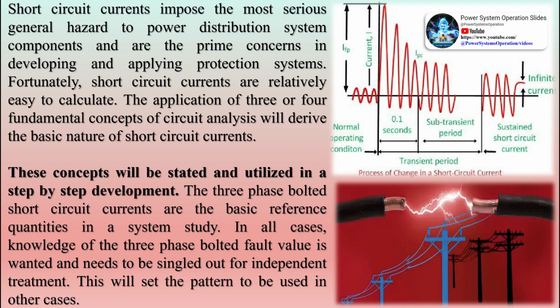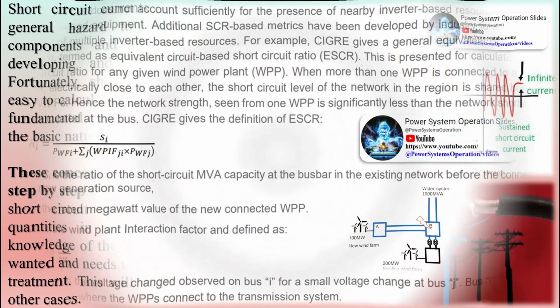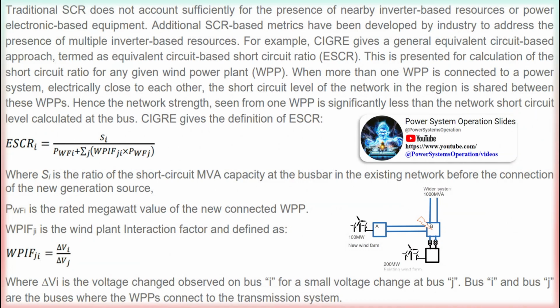A short-circuit analysis is used to determine the magnitude of short-circuit current the system is capable of producing, and compares that magnitude with the interrupting rating of the overcurrent protective device, the OCPD. Since the interrupting ratings are based on standards, the methods used in conducting a short-circuit analysis must conform to the procedures which the standard-making organizations specify for this purpose. The American National Standards Institute (ANSI) publishes both the standards for equipment and the application guides, which describe the calculation methods.